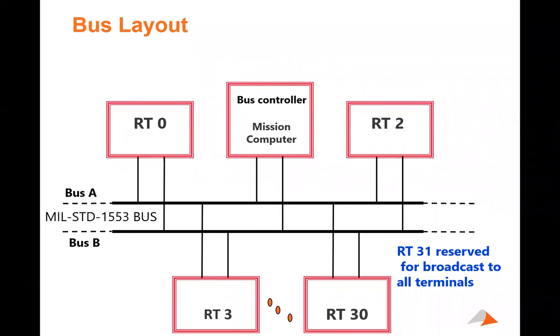The transmission of information on them can be alternated. In early designs, they used to transmit the message on both A and B bus. If you're in something that requires even more high integrity, you might look at that. But with 1553, with the ability of the terminals to see the message and then respond back that they got it, typically it doesn't need that, but it's a consideration.